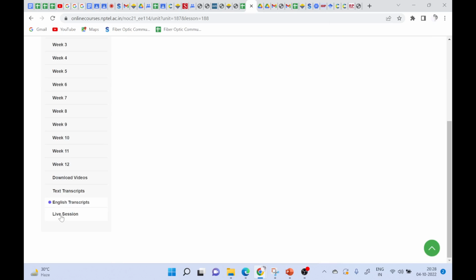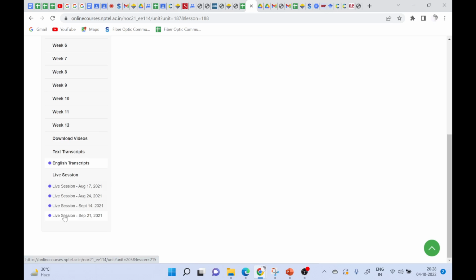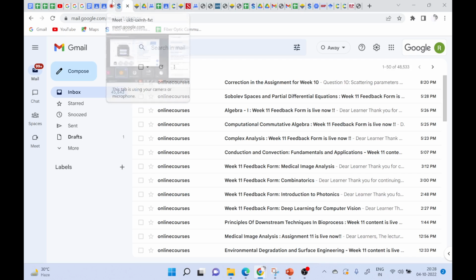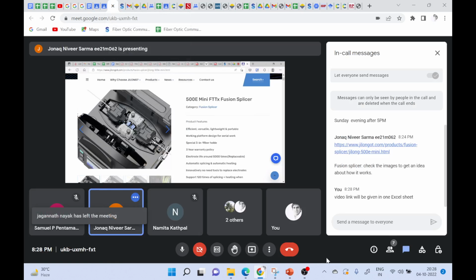Anyway, to use this splicing device, you will first strip off all of the protective layers and keep only the cladding and core of the fiber. You insert one fiber from this side and the other from the other side. The device will align the two ends and then apply an arc so that the two melt and fuse to become one continuous fiber.